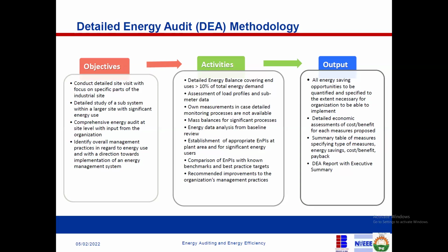Then what are the outputs? You have to detail all the energy saving opportunities. You must quantify them and write them out. You must do a detailed economic analysis. You must measure just what I did now: this is the saving coming from the refrigerator, this is the savings coming from LEDs, these are the savings coming from the bulbs, from this, from that.